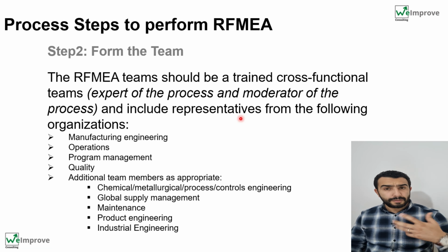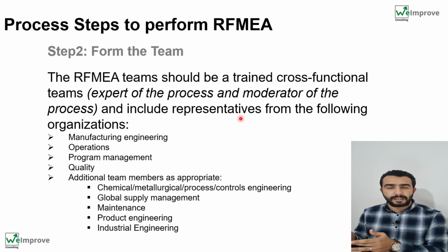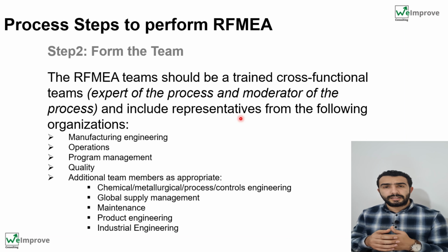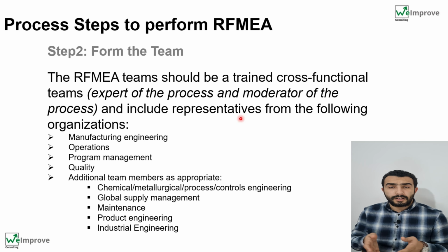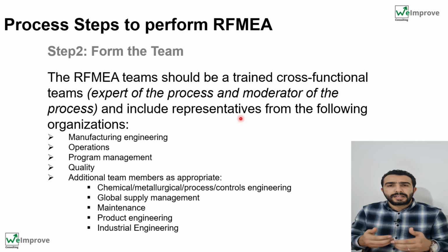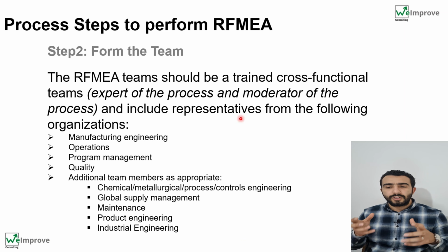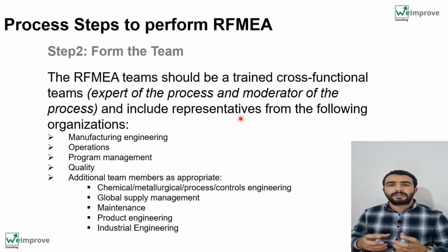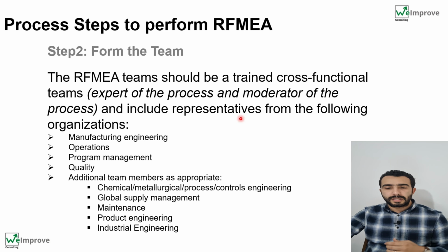But before doing it, obviously you have to form, train and build the team for every area. We need process engineers who have skills in the process. We need quality, we need a lot of people. But if they don't have knowledge of the FMEA, how will they control it based on the reverse FMEA? So at least they have to have the basic knowledge of the process, of the FMEA, and of the reverse FMEA, how to conduct it, which is a part of this training. So you have to form and build the team in order to have a good result at the end of this activity.